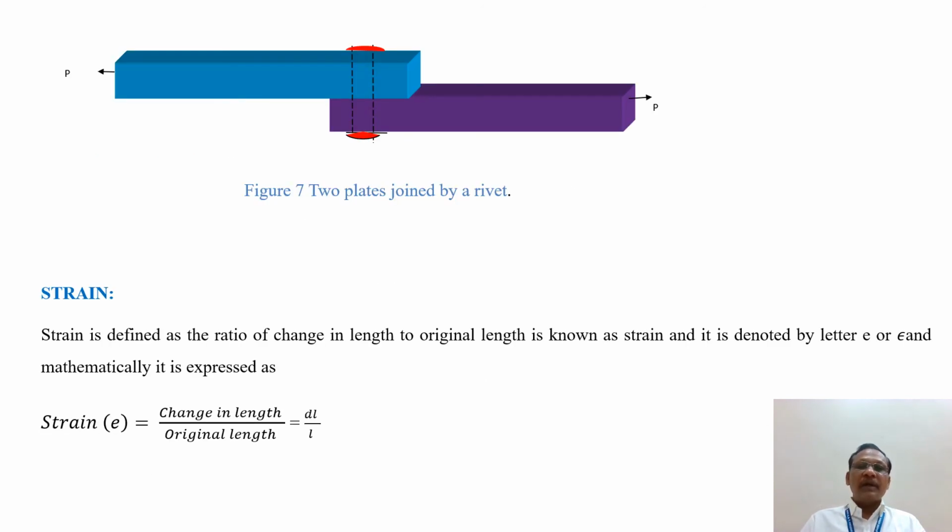So this is the bolt or rivet connecting these two members, which are kept in equilibrium. If the tensile force is applied on this member, then this total tensile force is transferred to this bolt and the bolt will fail here. This force is acting tangential to the cross section of the rivet. That's why the definition is written like this.